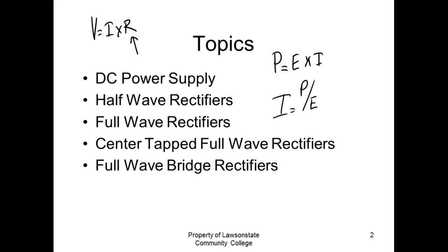The insulator determines how much voltage you can apply to it, because the higher the voltage, the more it's looking for ground, right? It's looking for the other conductor. So we put insulators on them to keep them from trying to conduct through air, right? You understand that? Or when they come in contact with each other. And plus now, if it's got an insulator on it, then I can touch the conductor, right? You understand that? Has nothing to do with that.